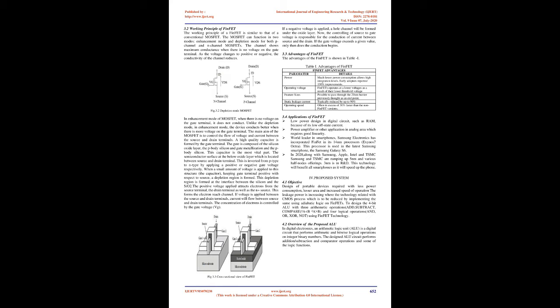Today's major concern in designing VLSI circuits has been the amount of power dissipated by these circuits. The adiabatic logic technique is becoming an answer to the problem of power dissipation. The term adiabatic refers to the change of state that occurs without the loss or gain of heat. The adiabatic switching technique reduces the power dissipation during switching events.